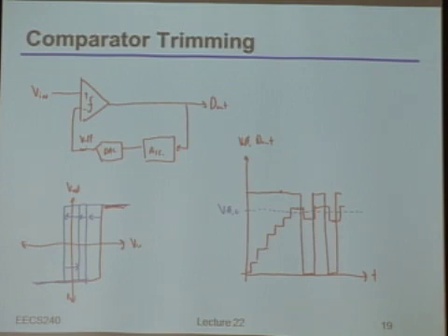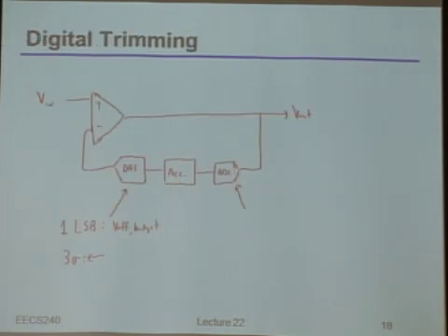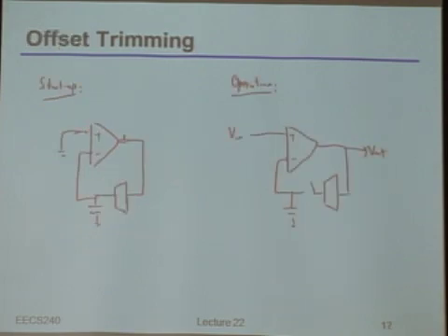Yes? If we were to implement this with just a regular amplifier and some comparators, so if you had an amplifier and another comparator, how do you know where to set the offset of that second comparator? Okay, great. So to quickly rephrase your question, what you're basically saying is, hey, look, this ADC, which maybe really is just a comparator, may itself also have offset in it. In other words, if this thing has an offset in it, then just like we said with the earlier picture, if there's any offset here, this output would converge to that offset and not necessarily to 0 differential output. Was this your question, by the way?